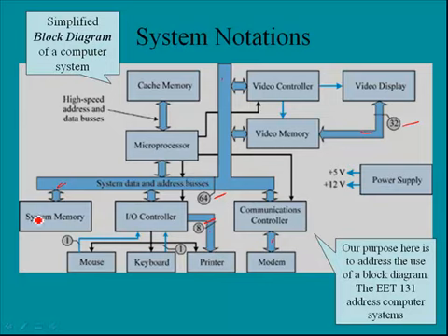Just as one example, from system memory to the microprocessor, there are actually 64 physical connections, so we can move 64 bits of data at a time. We'll pick this up later in the book, but 64 bits is equivalent to 8 bytes. So 8 bytes of data can be moved to the processor at one time because there is a 64-bit data bus here.